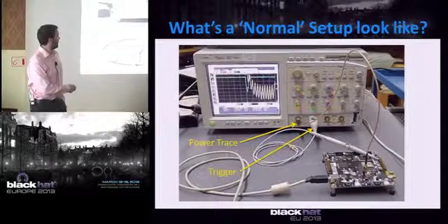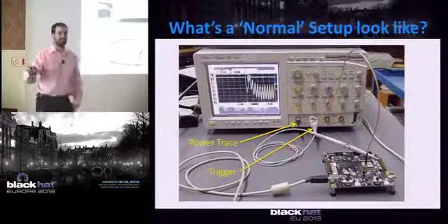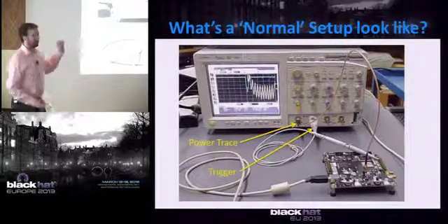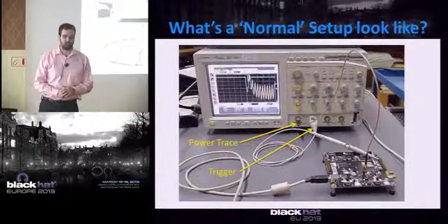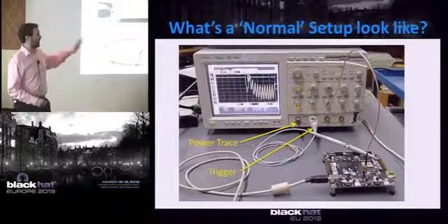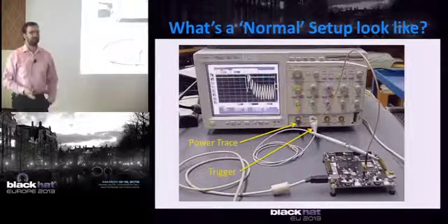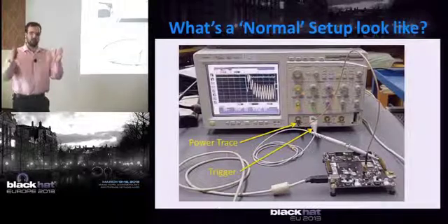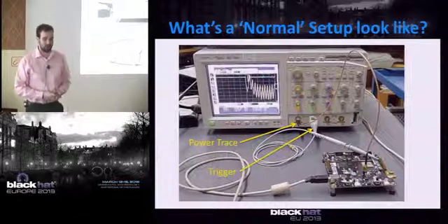It has a trigger pin. What this trigger does, and I'm doing the same sort of hack here, is tell you specifically when the AES is occurring. You might have noticed in that plot I said, well, way over here in this window, this is where the actual operation is occurring. I had to acquire a whole bunch of points because I didn't know where the operation was going to occur.